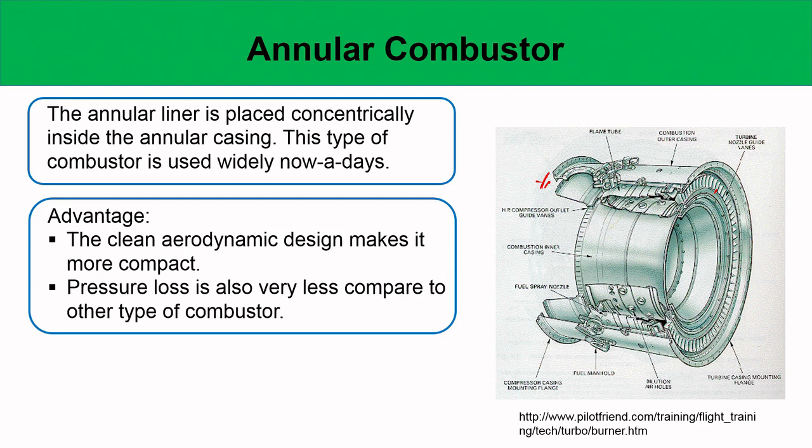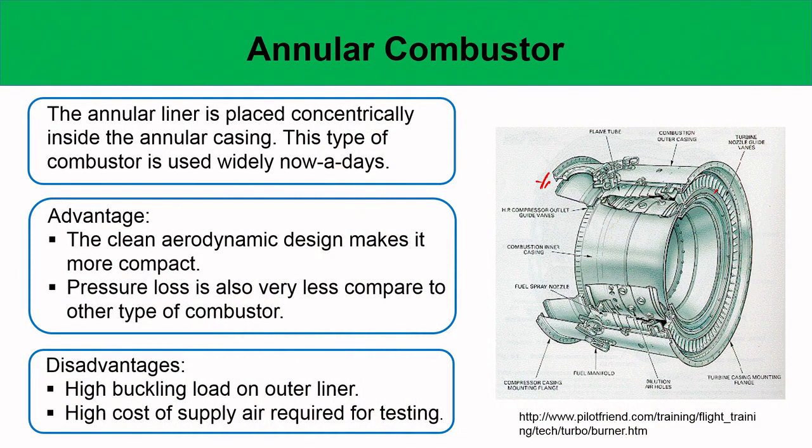Okay, because there is no separation as such and no intermediate walls, this combustor can occupy much less space, and it also has much less weight because it has totally done away with the cans. Now also the pressure loss is very small because you do not have much interaction with these walls, and more importantly, we can design this flow path aerodynamically in a much better way.